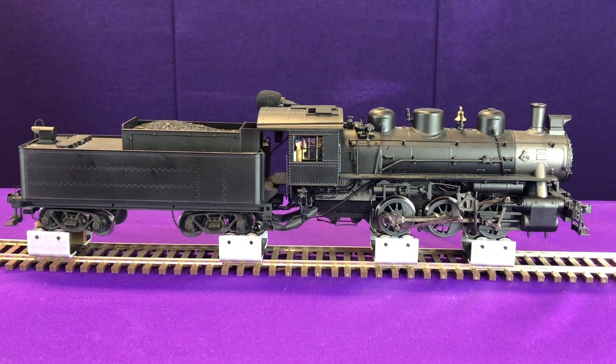And then to do this, we're going to set CV32 to a value of 2, and that's going to be the 2-dot part of our CV. And we've done videos on our YouTube channel about that, and we've talked about it in prior webinars as well. So CV32 to 2, and then with the locomotive running at speed step 1, we're going to set CV203 to a value of 255.